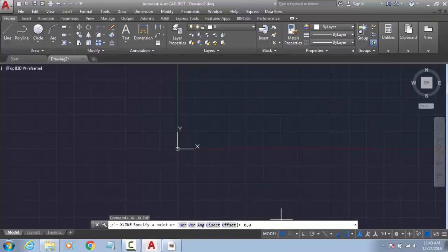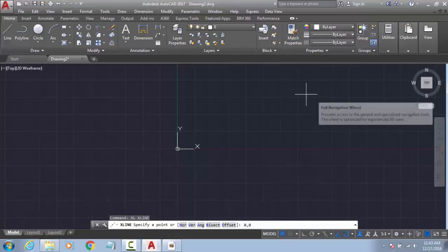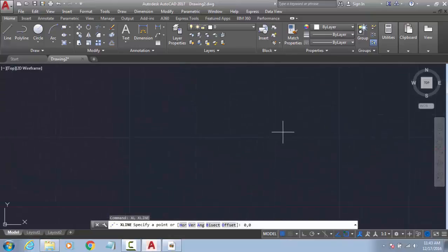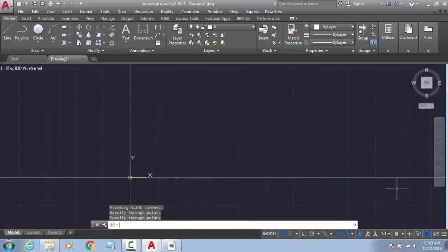This screen looks like a graph. When you used graph paper in childhood, you saw each small block counted as 1, and the big blocks counted as a bigger value. That means from here to here, it is 1 mm. Okay, I am going to make one line, and I am typing 1,1. That means it is going to make it, and again I am going to make 10,10.